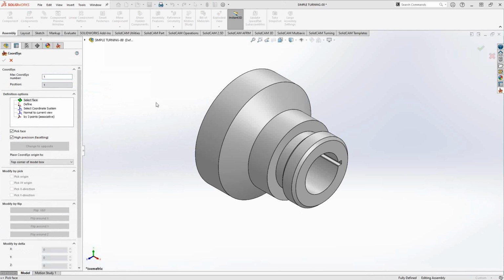So literally MAC1 position 1 will be XYZ, ABC, all at 0. If you have a MAC2, you're outputting the second offset. MAC3 is the third offset. If you've defined positions 2, 3, 4, so in this case MAC1 position 2, MAC1 position 3, what you're doing is you're defining an index plane of the part. You'll see that in the subsequent videos on our YouTube channel or in this introductory series on how to do some of those index planes.